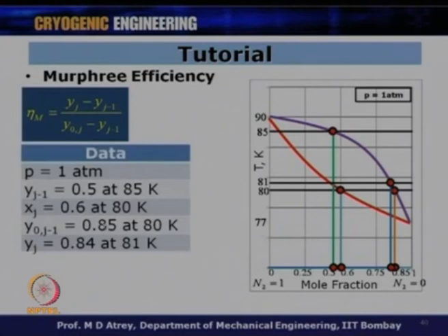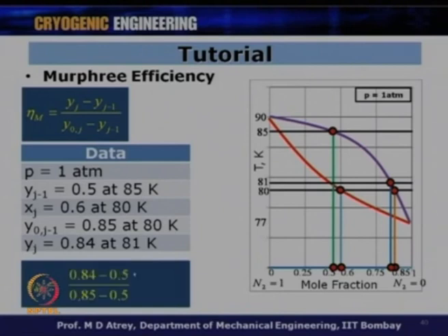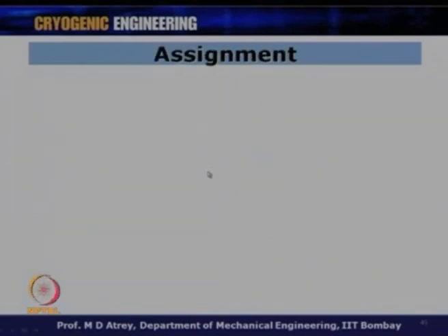Just to summarize what we did, isotherms or enthalpy composition diagrams have finite slope, indicating that the condensation or boiling of a mixture is a non-isothermal process. The separation is more effective when the difference in the boiling point is more. In a rectification column, a saturated vapor or saturated liquid or liquid plus vapor mixture is introduced as feed.